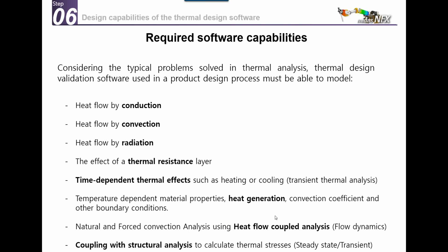If you have to do that, you need to have heat flow coupled analysis, because this is analysis coupled with flow dynamics, with CFD. So midas NFX can do that. You have a full coupling of heat and flow together. So you can simulate natural and forced convection. You can use fans. You can also use a lot of cool things that we added recently, like porous media and the MRF, if you know what it is, etc. Then coupling with structural analysis if you want to calculate the thermal stresses, steady state or transient. So these are all the features needed.